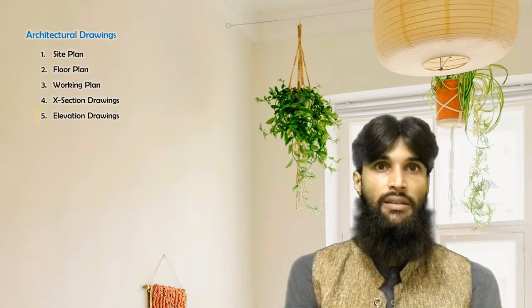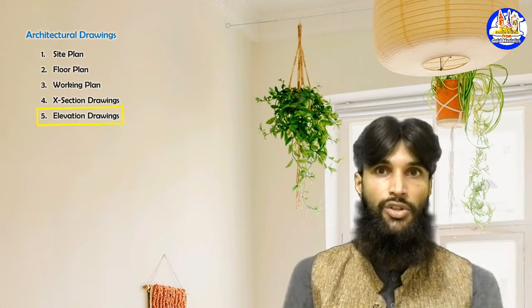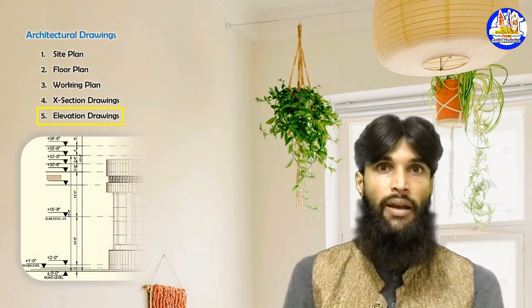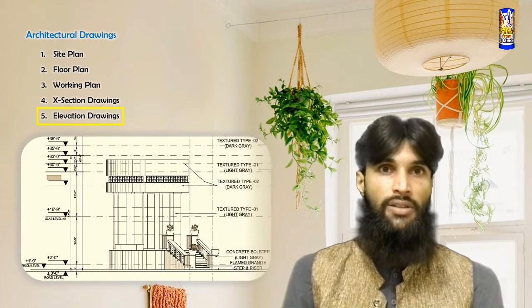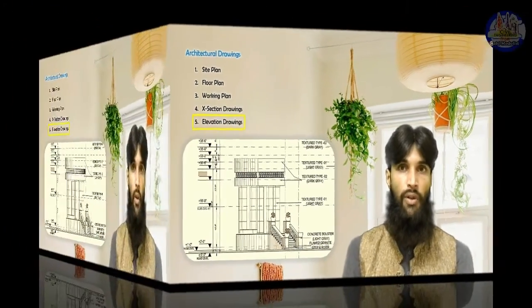Elevation drawings. These drawings contain the information of openings, size and shape of external surfaces and the height. They are prepared by having an aesthetic view of the building. They include the external and internal marking that includes the door and window sizes.